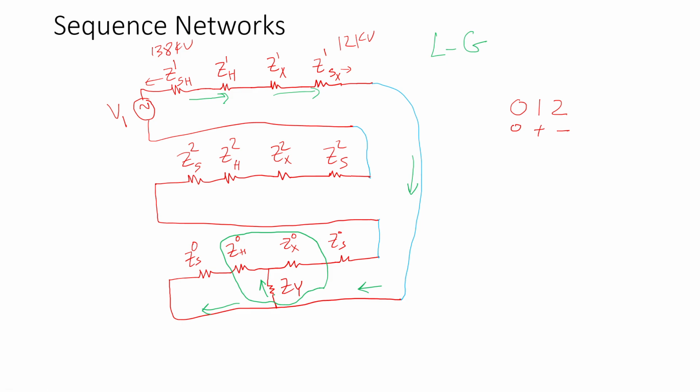So obviously, if you have a stabilizer winding, this impedance will be smaller than if you don't have a stabilizer winding. So this stabilizing winding has to be designed properly because it will see a lot of current.